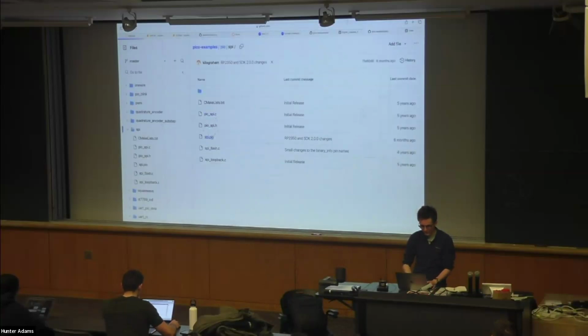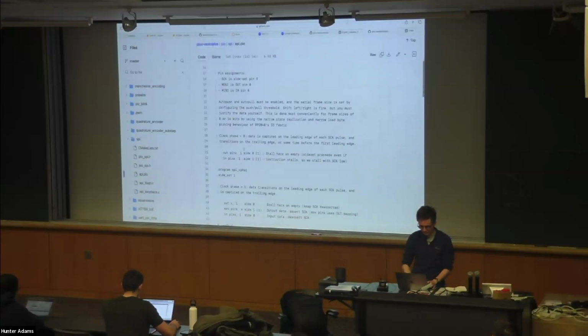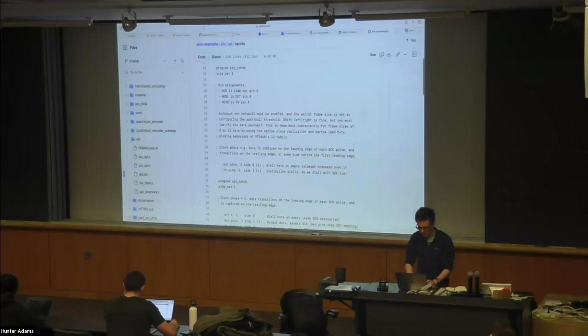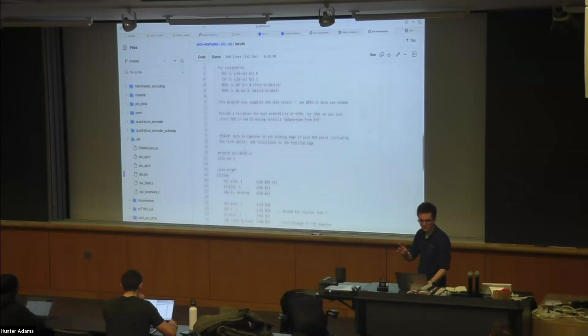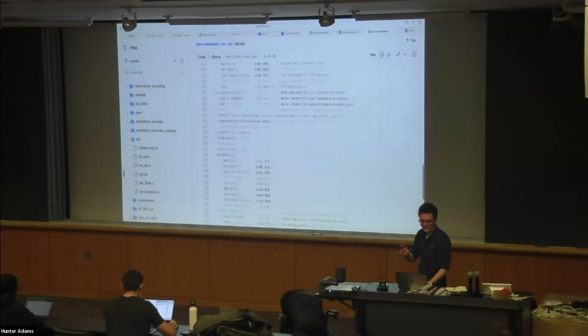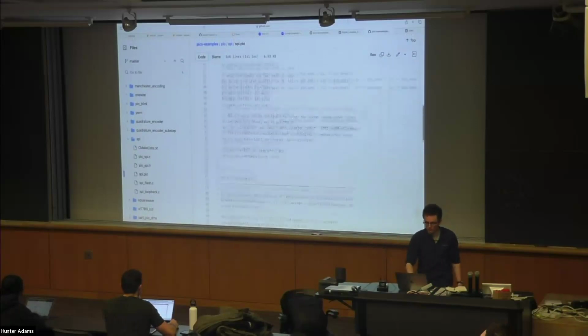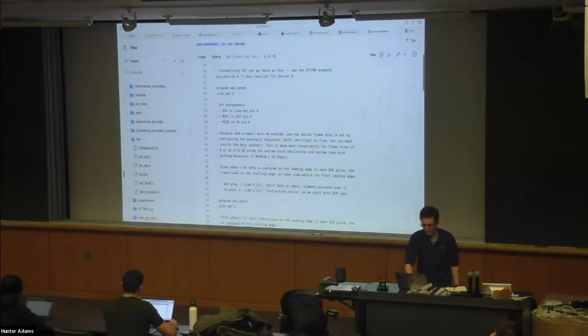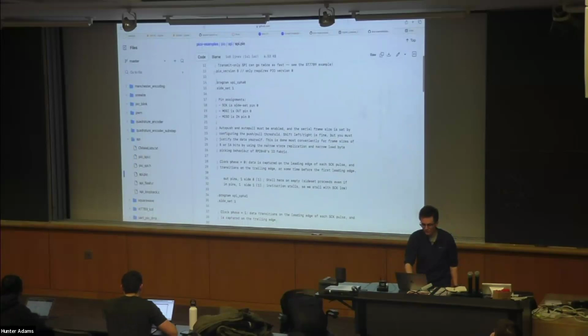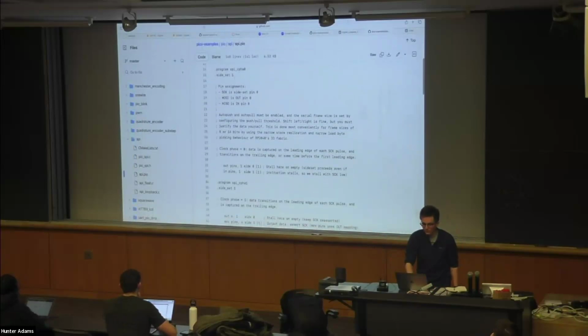So let's look at the SPI PIO. Look at this. It is only 2 instructions. Okay, so like I said, there's a few examples here with sort of increasing fanciness. It adds a chip select line or it changes the polarity and so forth. But let's just look at the bare bones example. Okay, bare bones example starts here. SPI, clock, phase, and polarity 0.